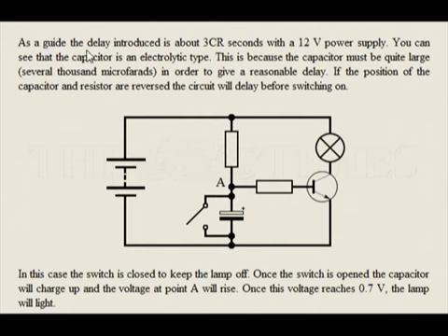As a guide, the delay introduced is about 3 CR seconds with a 12-volt power supply. You can see that the capacitor is an electrolytic type. This is because the capacitor must be quite large, several thousand microfarads, in order to give a reasonable delay.